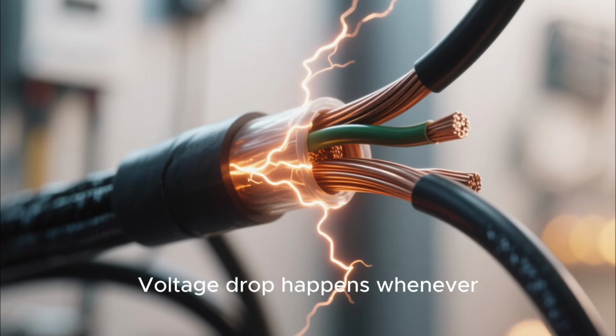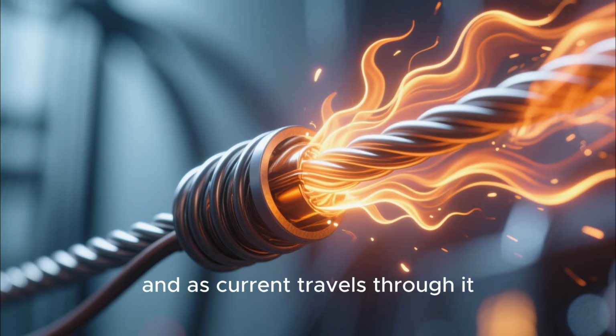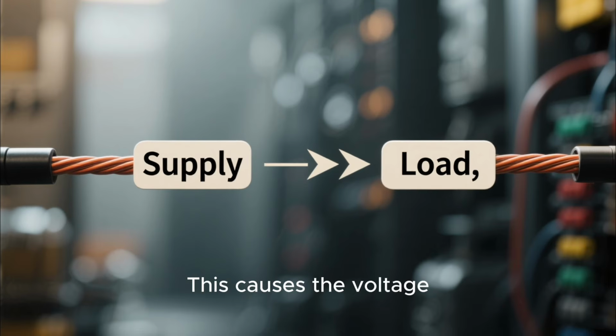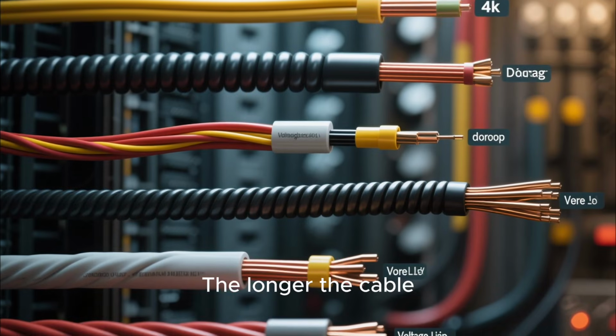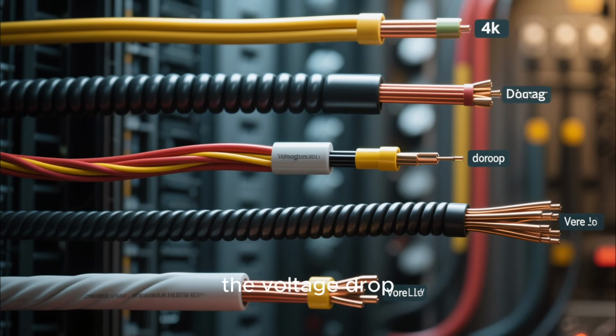Voltage drop happens whenever current flows through a long cable. Every wire has resistance, and as current travels through it, some energy is lost as heat. This causes the voltage at the load end to become lower than the supply end. The longer the cable, the higher the current, or the thinner the wire, the bigger the voltage drop.